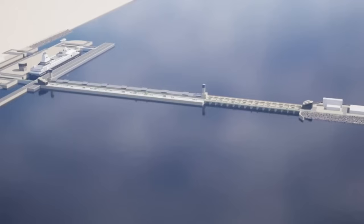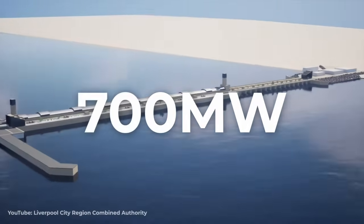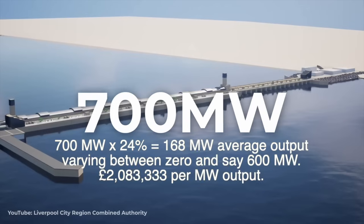Well, this is, or would be, the world's largest tidal barrage. It'd be 700 megawatts. That's the size of the turbines, not the power we get out. And it would put Liverpool on the map as having that world's largest thing. What prestige! You know, it's a terrific way to spend other people's money. So how much power do we actually get out of the 700 megawatts? Well, we can apply the 24% capacity factor, because the tides are pretty much the same as regards what we get out. So 24% of 700 is 168 megawatts, and that would vary between zero output and about 600 megawatts. But the average would be 168 megawatts.